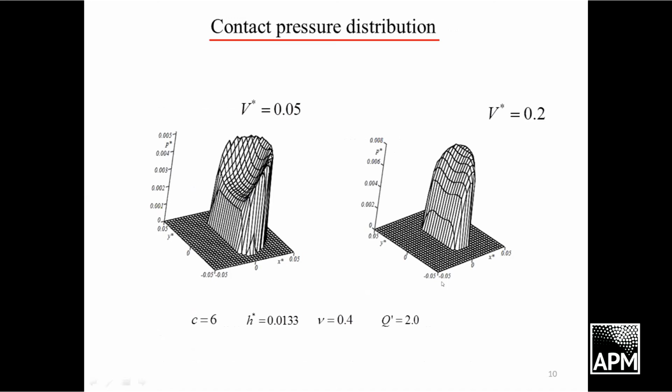You see, really, we have almost no dependence of contact pressure on friction. It is not very interesting but a predictable result, because for the case of low compressible viscoelastic solids, the same results were obtained for the viscoelastic half space.